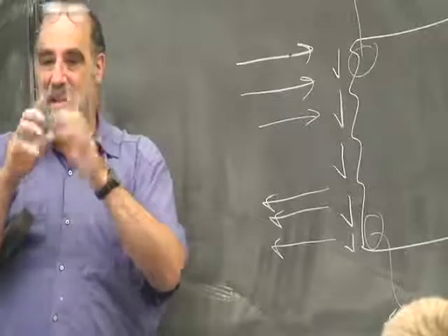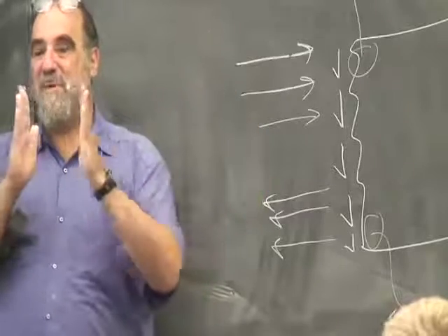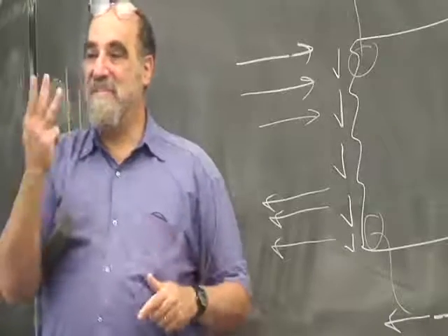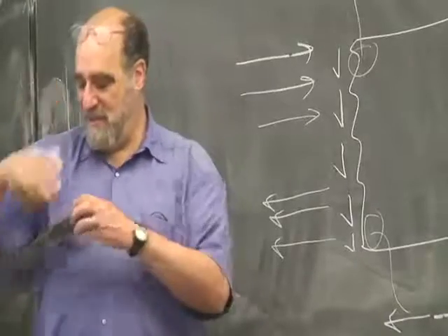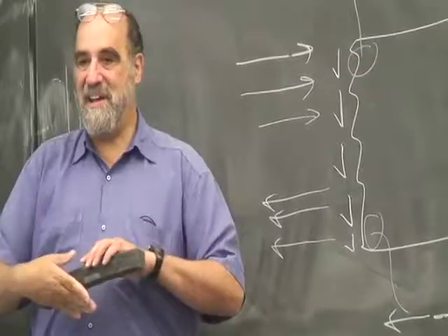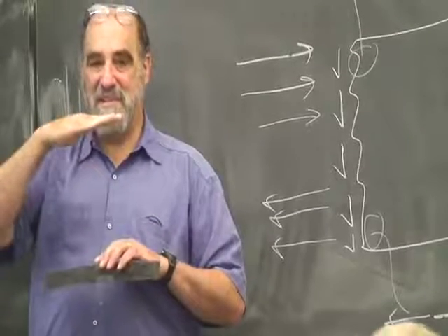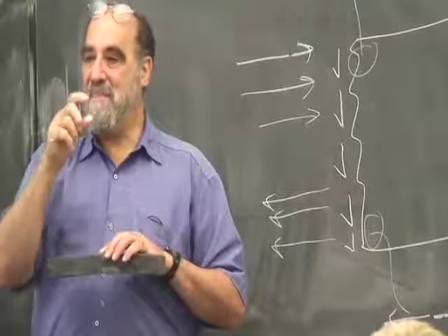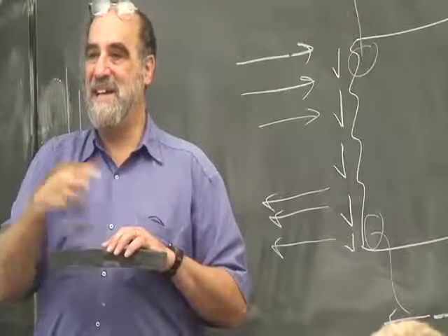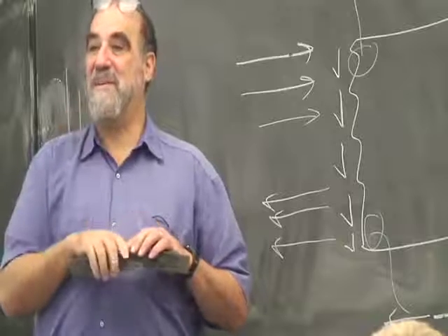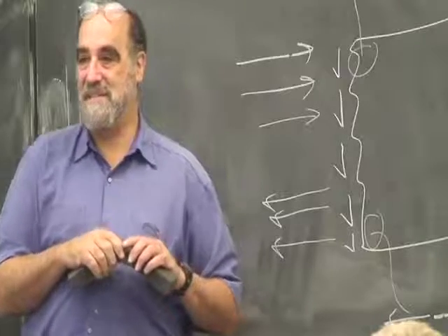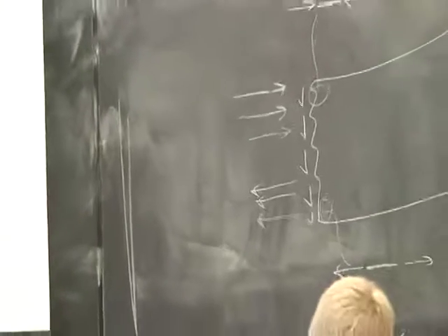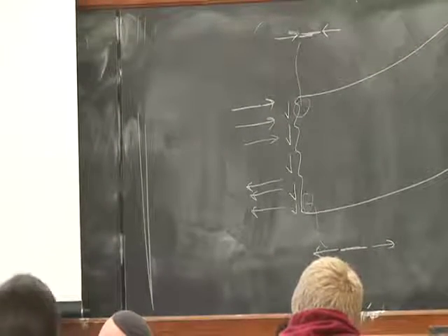So for a given curvature of this beam, we get more stretch in the fibers if H is bigger. So we have three effects which make this thing stiffer if it's thicker. There are more fibers, proportionality H. They have a bigger lever arm, another proportionality H. And each fiber stretches more, another proportionality of H. So that means the stiffness, the resistance to bending of this, goes as H cubed.